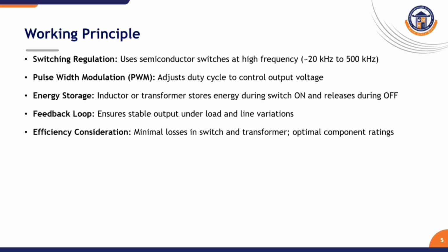During the switch on, the energy is stored in the inductor or transformer. During the switch off, the stored energy is released to the output. A feedback loop continuously monitors the output to maintain stability. Now, the efficiency considerations.